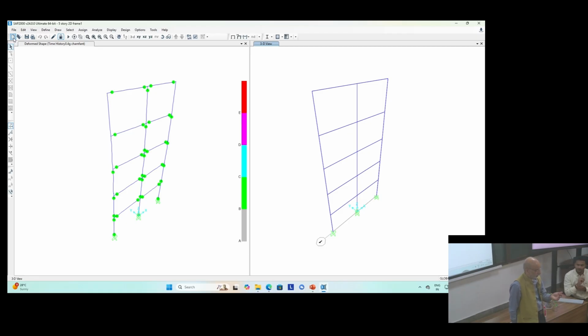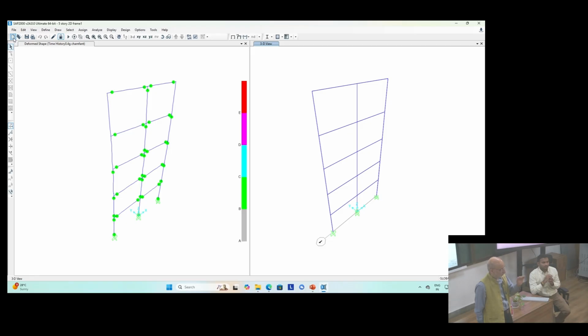So for the entire time, the frame you look for, you can see it all. And the second part will be the pushover curve. Whatever pushover analysis you have done is very important. So you will see how the pushover curve is generated, how the load is applied, how the load deformation will come, and how the spectral acceleration with the spectral displacement curve which we have been taught. So these are the applications. These are the two problem statements, and this is the data which we are using. So it will go side by side.